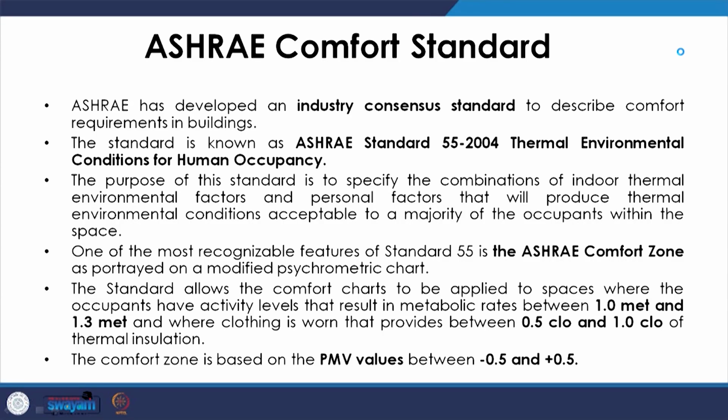Now, the ASHRAE comfort standard, which is ASHRAE 55, developed in 2004, defined all these 6 parameters to define a range of conditions which will be perceived as thermally comfortable. Now, this is not adaptive thermal comfort. This is based on PMV values between -0.5 to +0.5, and it defines that within this range of -0.5 to +0.5, people are most likely to feel comfortable.